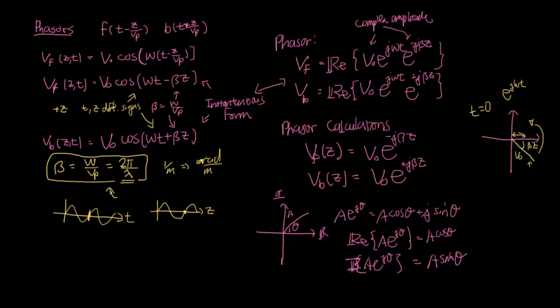So this combined with Fourier analysis is really powerful, because we can decompose any periodic signal into its constituent set of frequencies, and for each of these frequencies we'll have a complex amplitude. When we pass through a system we just have to see how this complex amplitude changes, and then we'll be able to describe the system. And if we want to describe the system for all time, we just perform the operation and convert it back to instantaneous form. So let's wrap up by outlining the steps of how to go from one form to another. Let's clean up a small corner of this board.